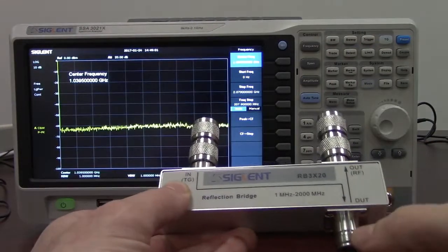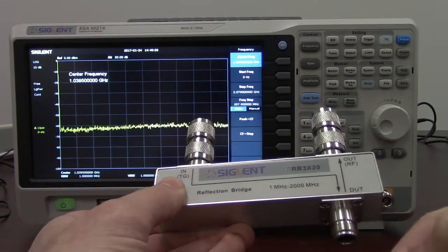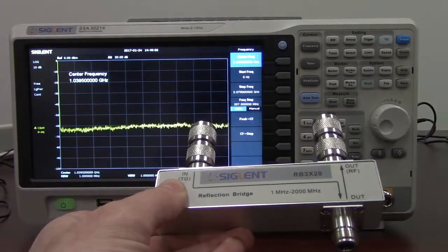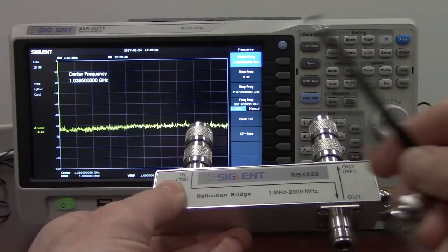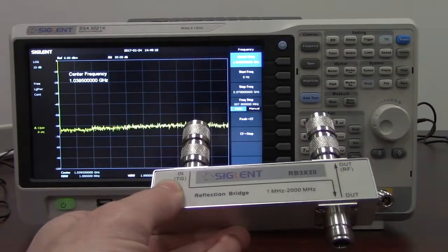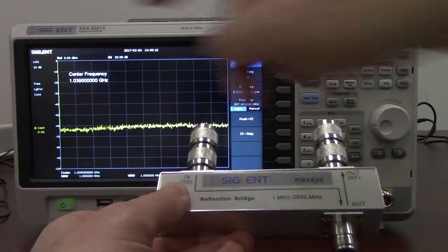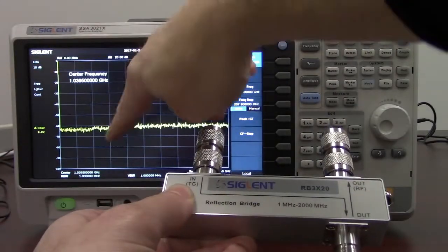That is going to then measure as a high value in amplitude as we sweep across the frequency range. As long as that impedance stays very mismatched, it's going to show a straight line. When that impedance is matching, so there are frequencies, we hope, where this particular antenna is going to resonate, it's going to actually pull energy out and radiate.